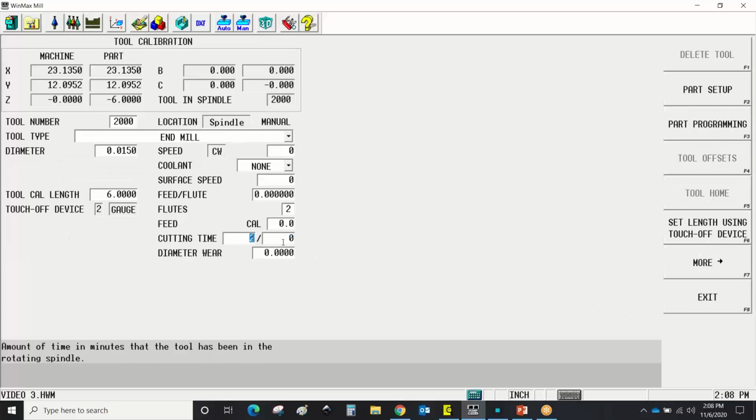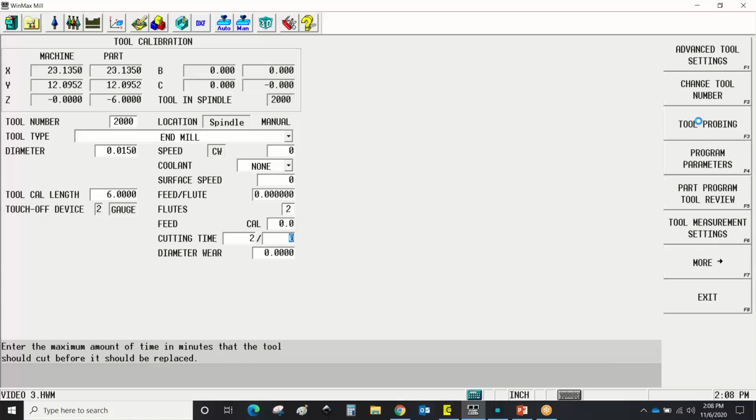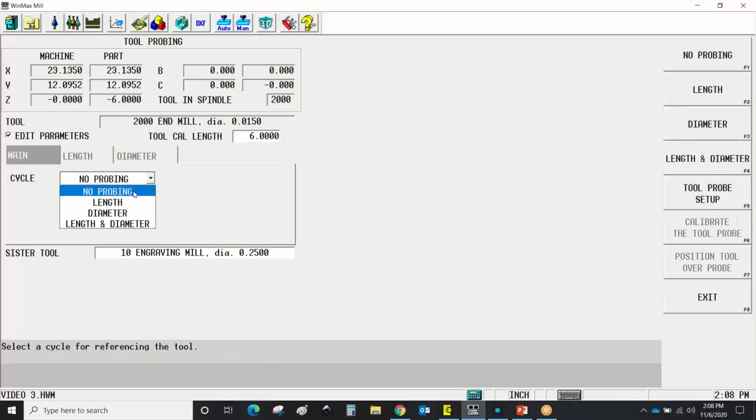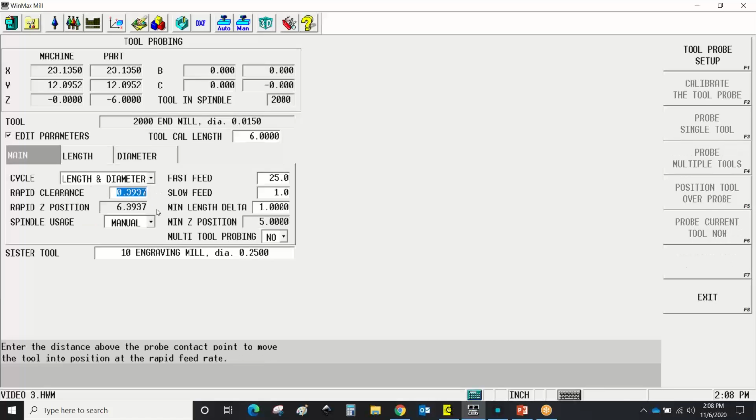And for each tool, we have this same setting here. So for tool 1, I could have sister tool 10. For tool 10, I could have sister tool 100 or whatever. So I could continue this on if I need to. One of the other benefits to having the probing, however, is I can also, if I set it up to probe for length and diameter, for example, somewhere else in the control, which we've talked about in one of the other webinars, set a tolerance for length and diameter, which would also trigger that sister tool because the tool has become defective.